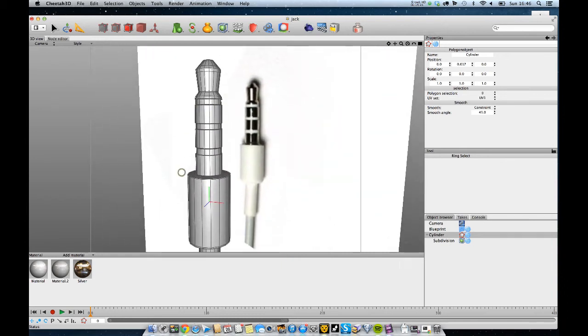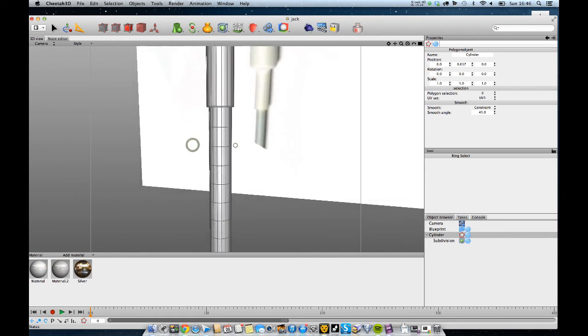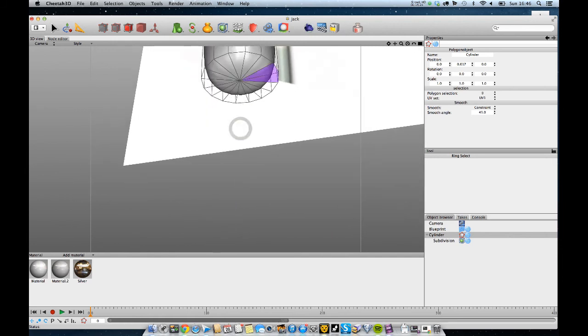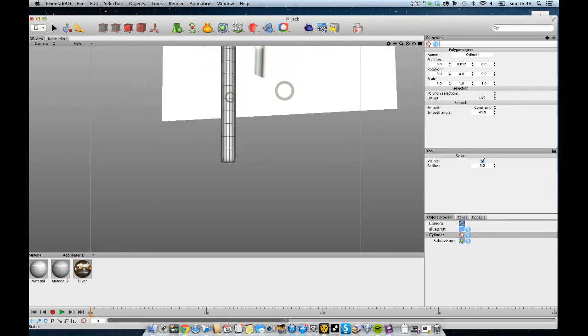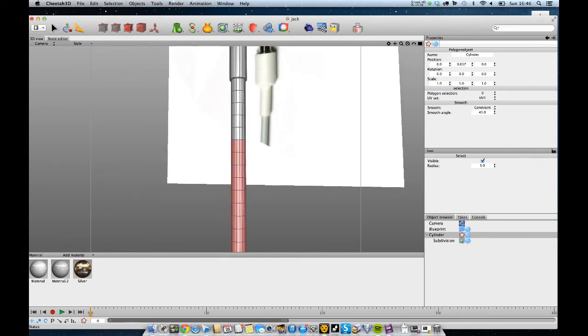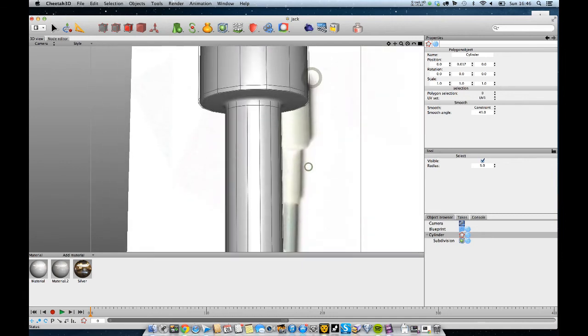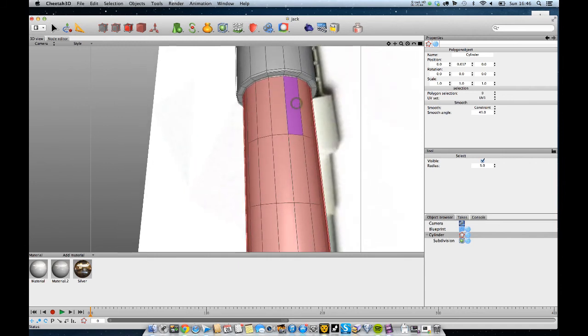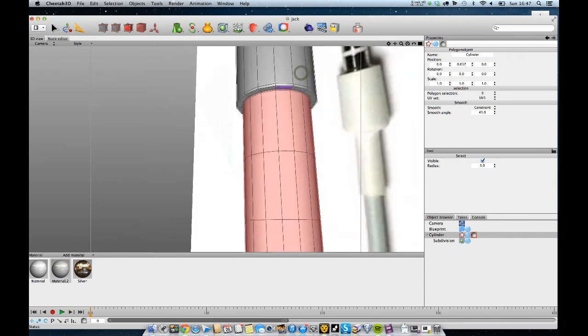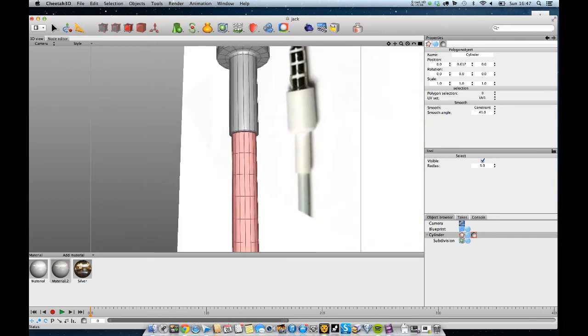So what I'm going to do is let's do the cable first. That's the easy one, this grey down here. So selecting these polygons here. Oh, it's not going to let me. That's what I want there. Just draw around them. Right, I'm going to press Apple Shift X, which we've used a few times, and just keep increasing that selection. Okay, and just coming close now because I want to make sure I've got the right bit. See, I want this to go one more polygon set, and let's throw that grey onto there. Perfect.